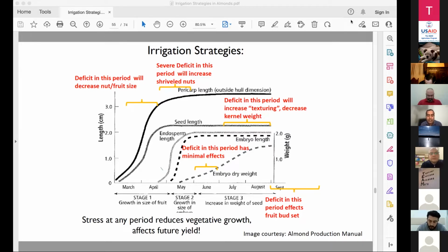Once you have the proper conditions for planting, you plant the trees and immediately water the trees. By that time, we already have the irrigation system in place. If we don't have the irrigation system in place, we hose down. We bring a hose with a moving water tank and apply a good amount of water to the newly planted trees. One, that gives the tree enough moisture for the proper settlement of the roots.